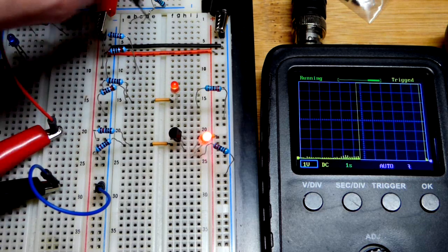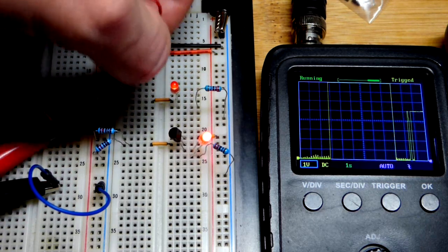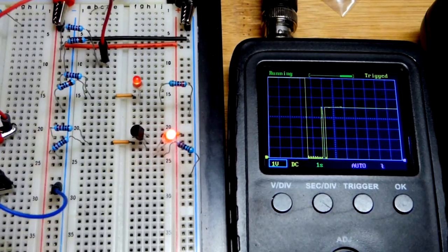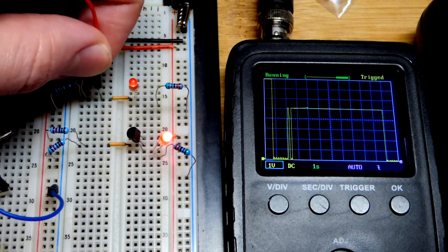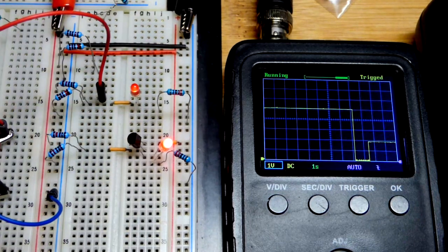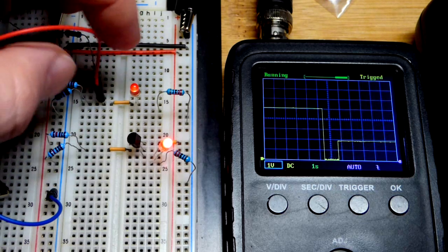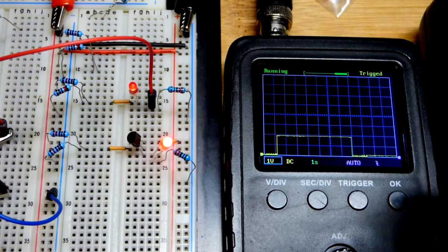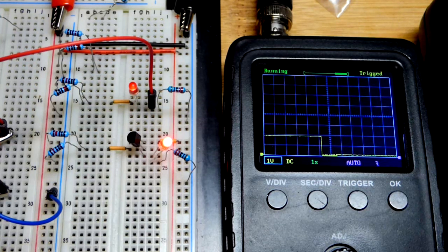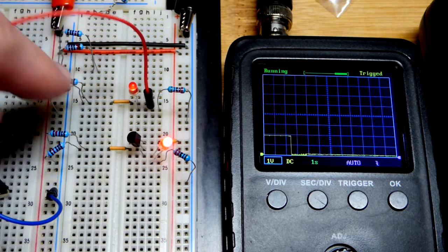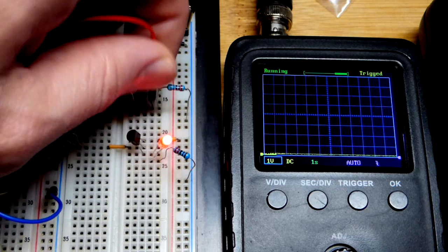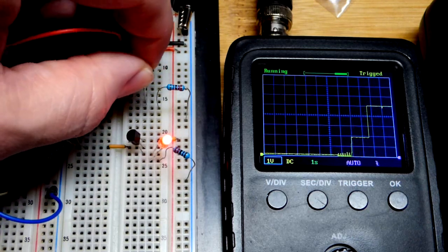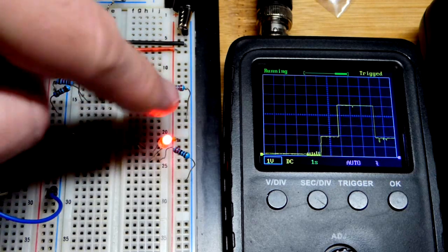And so we'll go up to this voltage divider, and there you can see we got that 5 volts right there. Pretty nice. Now we'll go to the circuit with the LED and its protective resistor. So that's the vast majority of the voltage is across the LED. If we go across the resistor, which remember sets the current, there's almost no voltage across the resistor. There's a little bit. So we're losing too much current from our voltage divider there. And we come back, if I yank the LED, you can see it jumps up. So it's that current path that is pulling it down.